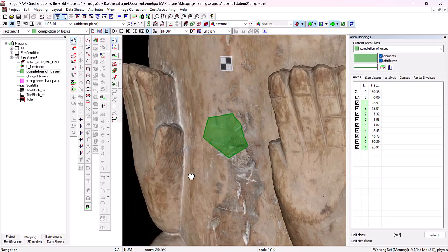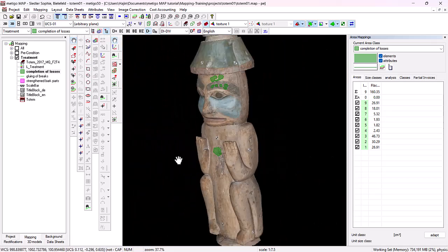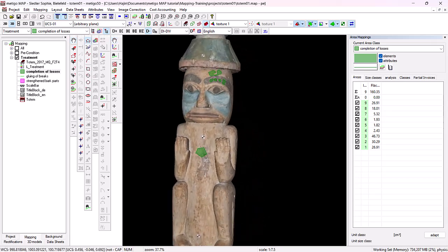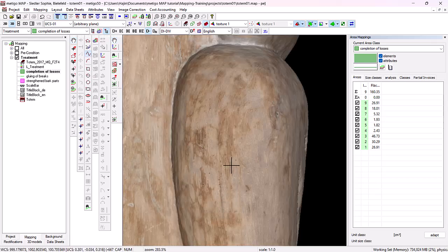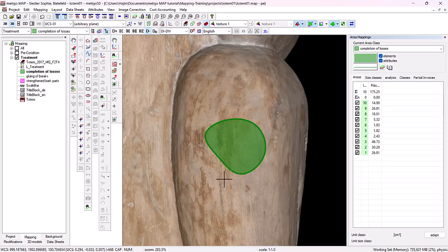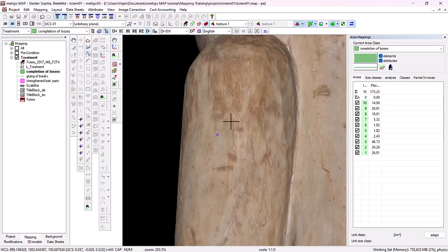So during 3D mapping, it's always good to use the spacebar to interrupt the drawing command. That means I have chosen my spline here, I press the spacebar and double click here left and can draw my new entry here. Right mouse button to close. I press back to my overall object display. I can navigate to a new position, double left click, release spacebar, and can draw a new area.